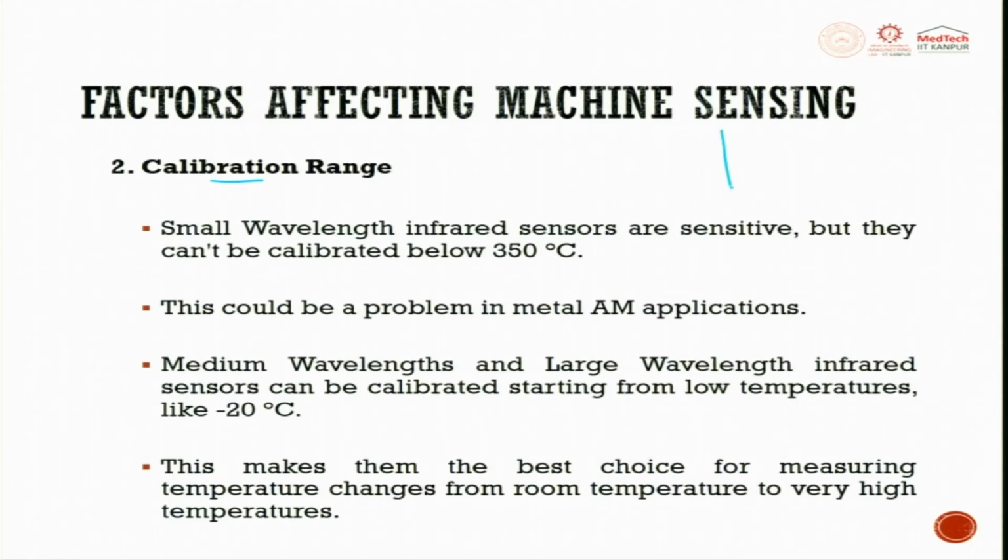Calibration, when we try to do a calibration between y and x, it can be any parameter. If you have a chart like this and then somewhere it is linear and then it is non-linear, we should always try to choose the linear portion of the sensor. So, from here to here you might have non-linear and again non-linear. The sensor has to be chosen in one particular range where their responses are linear. Now, with this linear response, you try to do calibration. When we try to do calibration, we try to do an indirect measurement on the output whatever we want.